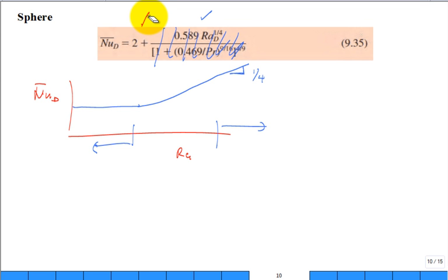And somebody says, how does that come about? Well, when you have very low Rayleigh number, what is that? It's very still fluid. The fluid's not moving. There's negligible buoyancy effect. We already studied when you have a sphere of radius r, let's call it r1, and you insulate it and you put around it a layer of stagnant insulation of radius r2.